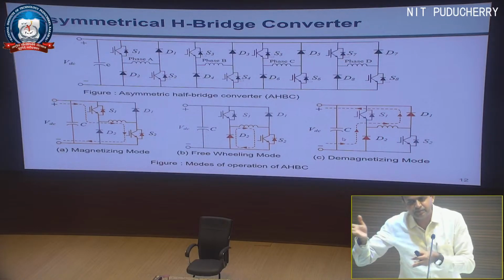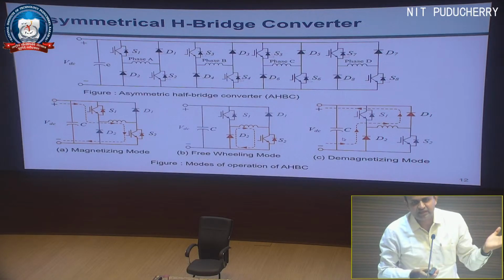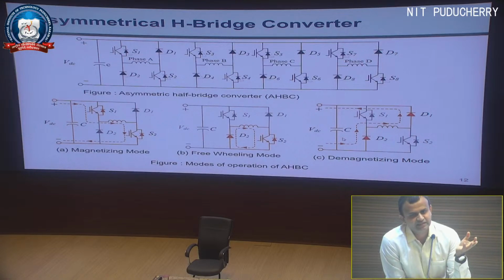For thyristor it is PN, right? And then comes the way in which you are playing with the carriers, right? Majority carrier, minority carrier, that decides. And then there is voltage control, current control, right? So in the case of MOSFET, the inherent diode is present, so you don't need to add one. It can be used very well for trapping that stored energy.